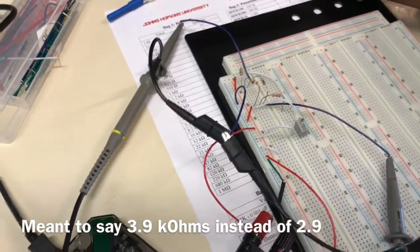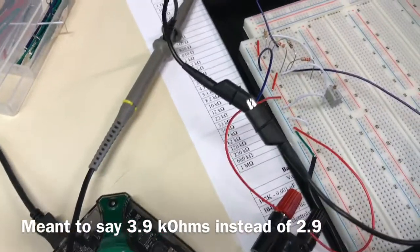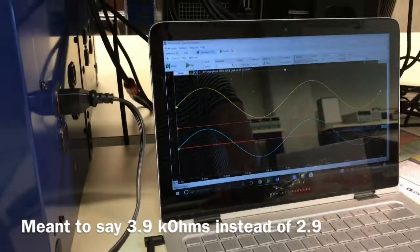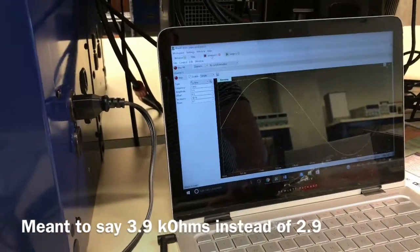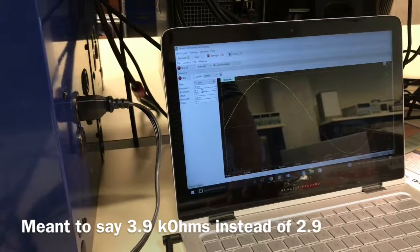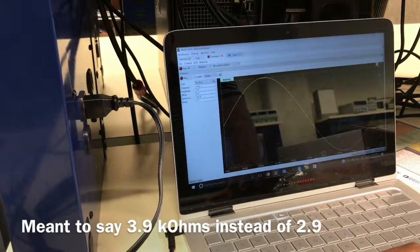So when we run the wave gen and generate the signal, we'll start by running the wave gen at a frequency of 1 kilohertz and a peak-to-peak voltage of 10 volts, so an amplitude of 5.